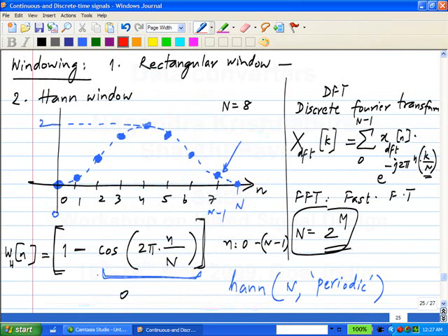Okay, you take your 1024 samples and multiply it by this one. So that is, you are passing it through the Hann window. And then you take the DFT. But the multiplication and all that will happen in the post-processing tool. Okay. It's not something you have to implement into the A to D because it's very easy to analyze it. There is no point wasting hardware trying to implement it.